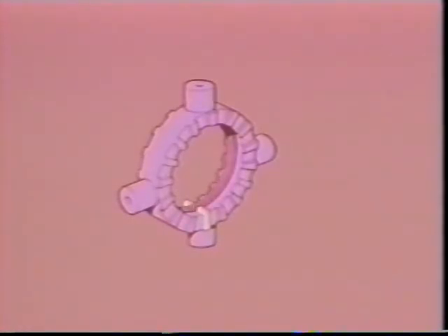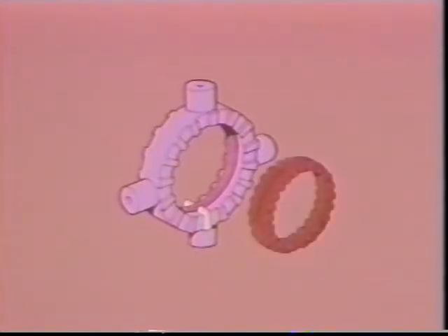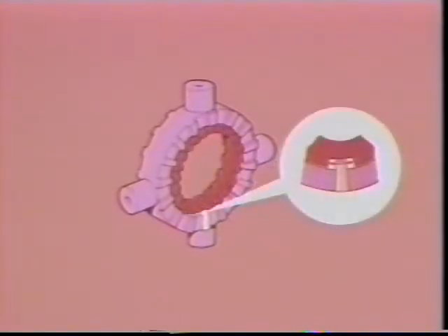A snap ring fits into a groove on the inside diameter of the cross and also fits into a groove on the outside diameter of the center cam when positioned inside the cross. The narrow slot of the center cam fits the key of the cross when assembled. The slot, which is wider than the key, allows the center cam to rotate, but just a short distance. The driven clutch member fits on either side of the cross and center cam assembly.